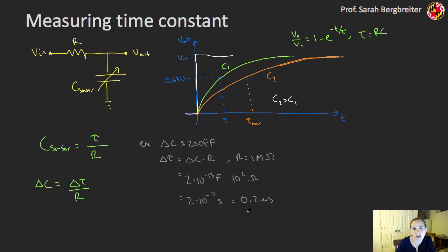And this is a pretty big ask for the Arduino, for example. For the clocks on the Arduino, if you have a faster computer, this might be pretty reasonable. But this would give you kind of a lower limit. You're looking at something on the order of tens to 100 femtofarads as your kind of capacitive resolution using this kind of method.